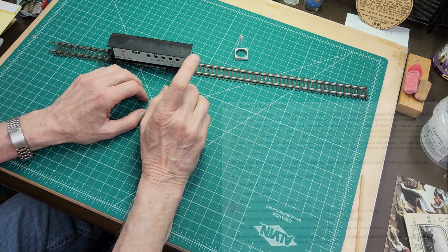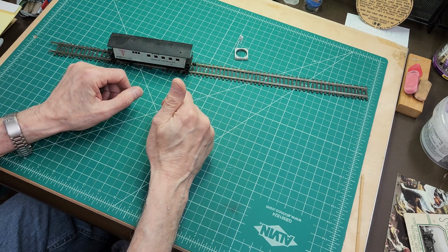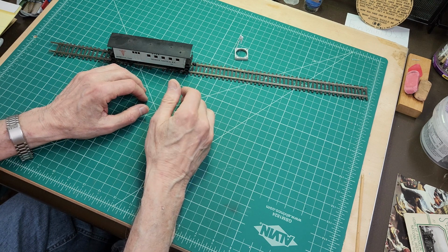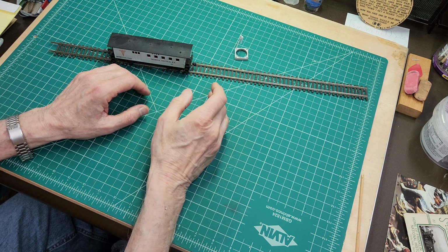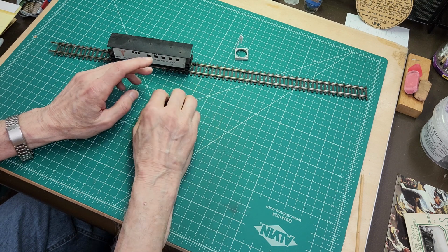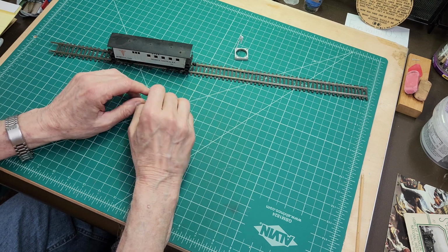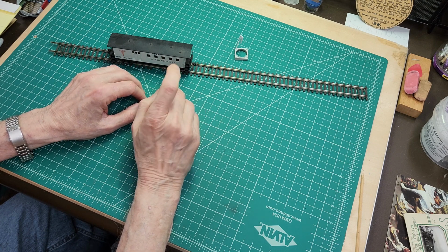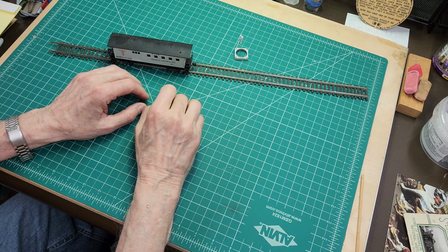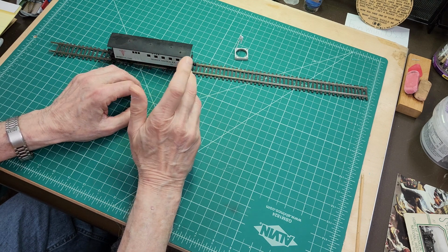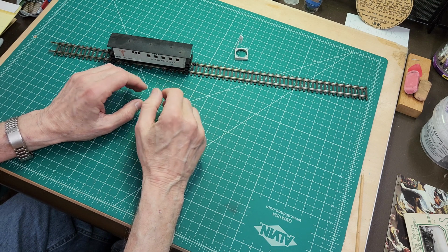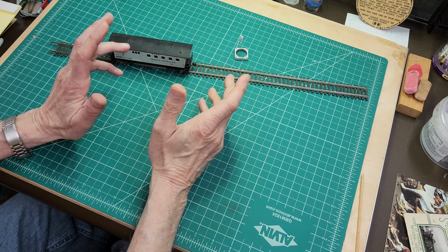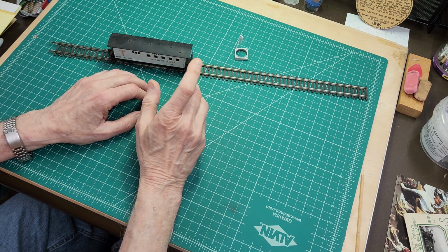But I also considered that perhaps the endpoint at 1, the interrupt input port, was being used for input instead of the port on 2. So I considered both. And what I discovered is that every example that is supplied with the library has unique port numbers, and worse, the library doesn't have the ability to interpret this duplication of endpoint numbers that I have coming from the NCE interface board. I'll show what I've created and what the results are.